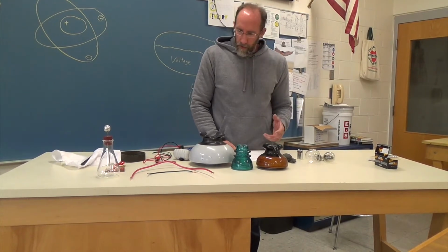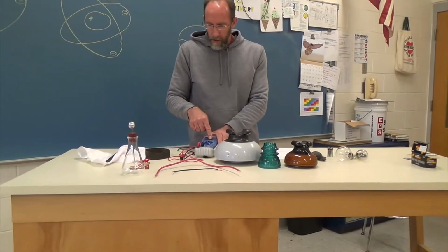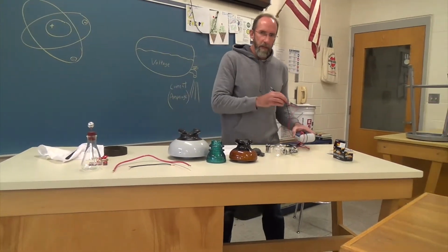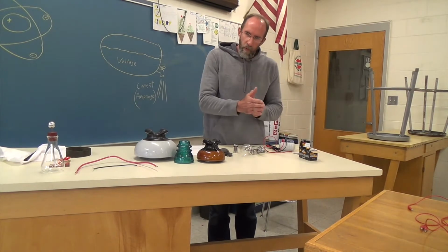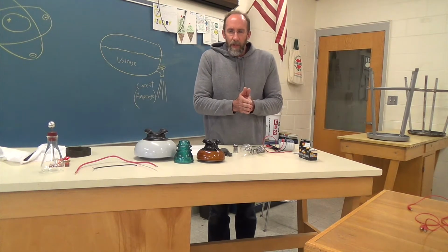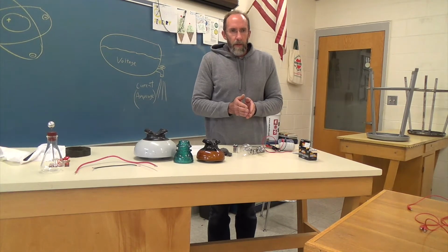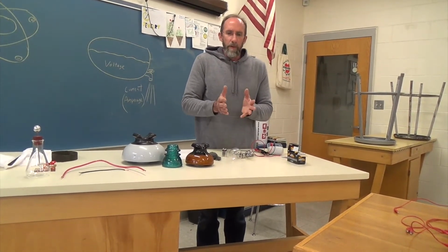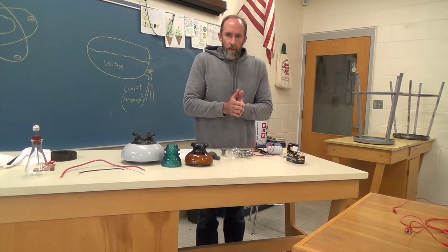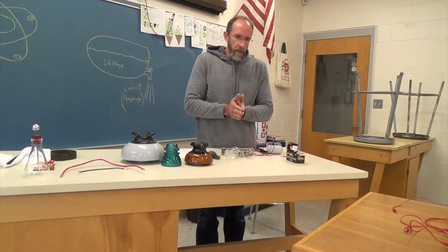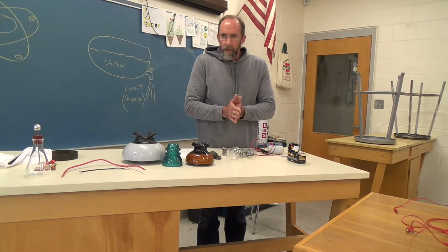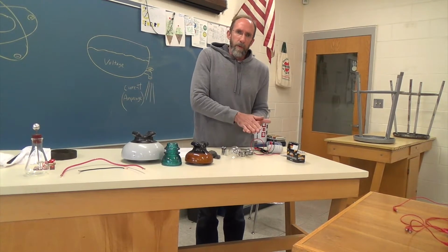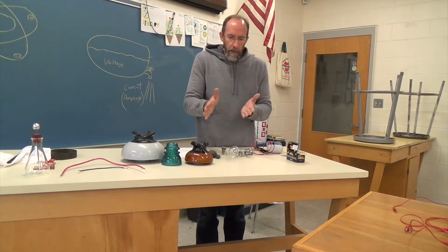resistance is the next thing. So we saw that we were getting zero resistance on here, meaning there was good conductivity. Resistance is sometimes something that slows down the flow of electricity. When you're trying to force electricity through a conductor, and maybe the conductor is a little too small, basically the electrons rub against each other and they create friction, and friction creates heat. So electrical heat is from resistance or electrical friction. And that's beneficial. You can use that to convert electrical energy into heat and even light.